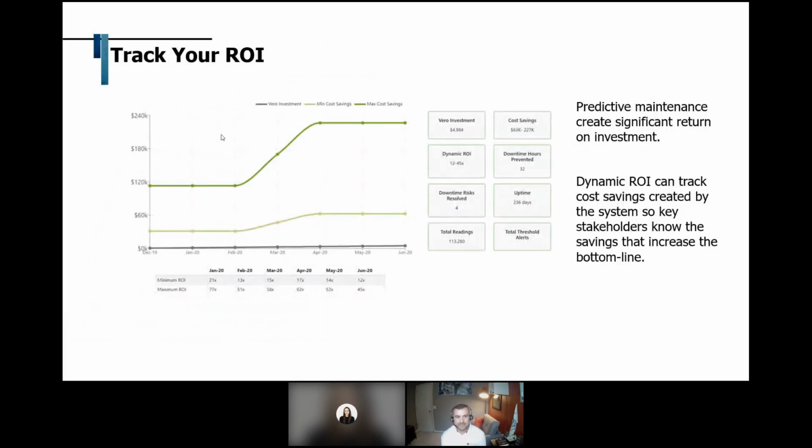So a big part of that is understanding the cost to your company. So understanding all of your maintenance labor costs, understanding your repair and replacement costs, and then understanding what downtime hours are for a piece of equipment. If it's a piece of equipment that shuts down the whole facility, then I'm sure it's extremely high. And also understanding a piece of equipment that might just shut down a part of a line or a line in general. Being able to put that into dollars and cents will enable you to count the hours and maintenance costs behind that.